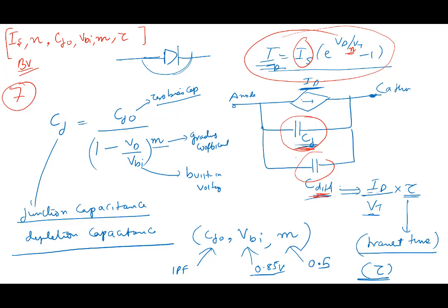In a PN junction also, if you apply a very fast sinusoid across a PN junction, it's not going to rectify, because it takes time to charge and time to discharge. The PN junction will not rectify. So all speed limitations are why these capacitances are so important. Without the capacitance, you can understand a diode simply by saying, well, it does this, it does that. But if you want to understand in a deeper manner, you have to know the capacitances. Without that, you cannot predict anything about the speed of a transistor or a diode. Okay? So that's the forward bias. And we'll stop at the reverse bias part.